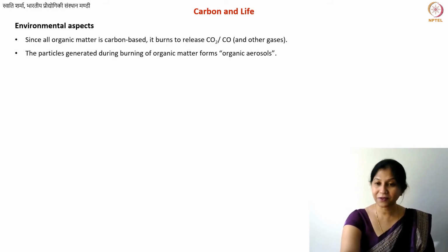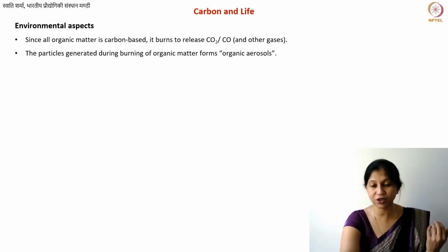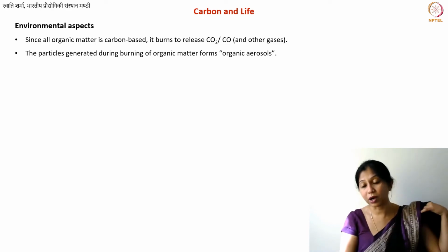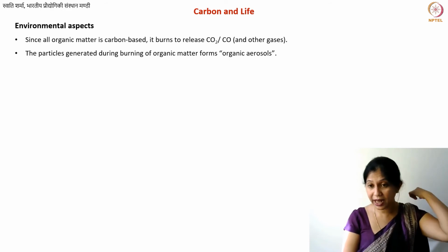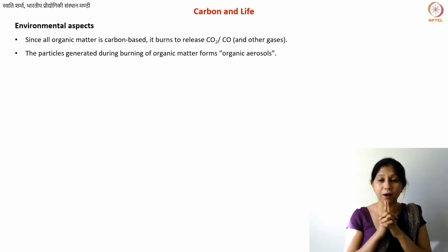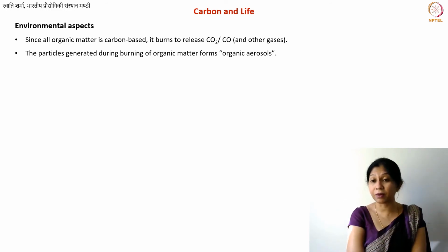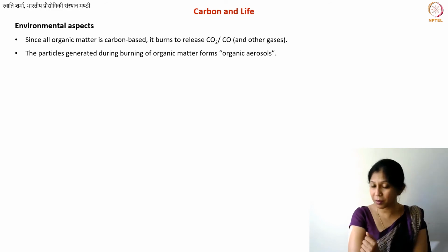But if you don't have sufficient oxygen, or sometimes the burning is happening very fast, so even though there is a lot of oxygen in the environment, because the reaction took place extremely fast, not all the organic matter was able to convert into carbon dioxide. In that case, you will also have carbon monoxide. You will also have some tar-like particles. These tar-like particles basically result from unburnt or semi-burnt carbon particles or organic matter, and as I said, these are heavier. So these tar-like particles end up forming organic aerosols.